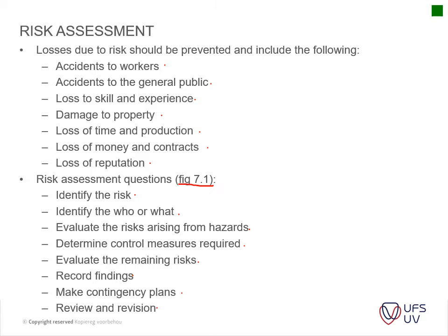These risk assessments are cardinal to health and safety. Usually your health and safety consultants start with a baseline risk assessment, and each month they do an audit and identify risks. But that doesn't mean that we as construction managers should not look at risks. For instance, some companies have ISO regulations which require you to look at your risks at least every 2 weeks and not monthly, but that is dependent on each company.